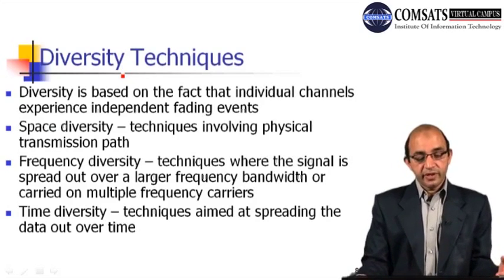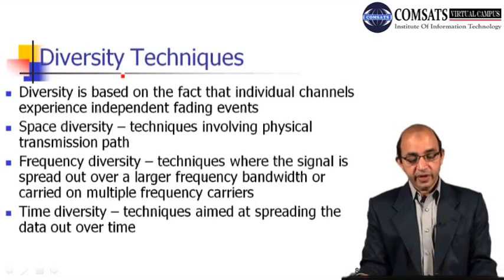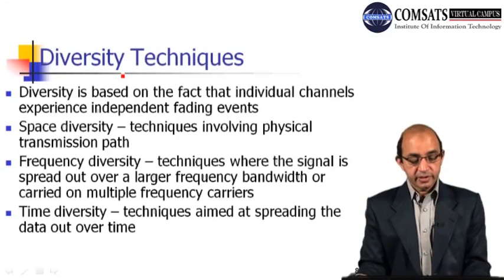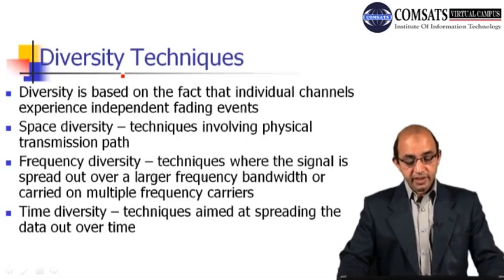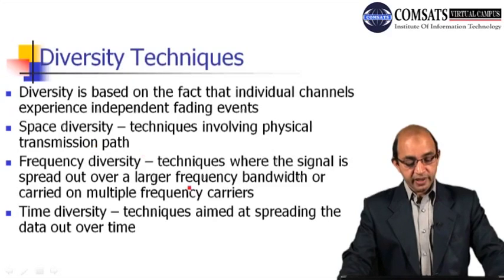Then we can also have the diversity technique. This technique is based on the fact that individual channels experience independent fading events, right? So there can be space diversity, techniques involving the physical transmission path, and then we have frequency diversity, techniques where the signal is spread out over a large frequency bandwidth or carried on multiple frequency carriers.